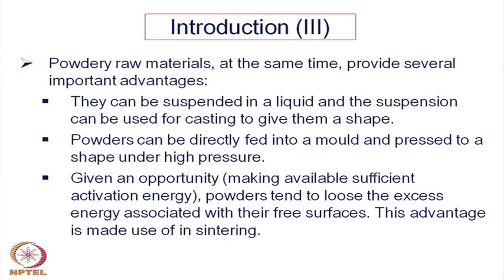They can be suspended in a liquid, and the suspension can be used for casting to give them a shape. Although they are not plastic materials and cannot be melted, these powders can be suspended in a liquid medium, maybe aqueous or non-aqueous, to form a viscous slip that can flow and fill up the cavity of the molds. One can therefore develop casting techniques not with molten material but with suspensions of fine powders, and that is a very common technique, from slip casting to gel casting and tape casting and so on. So powder materials have their own advantages in that context.